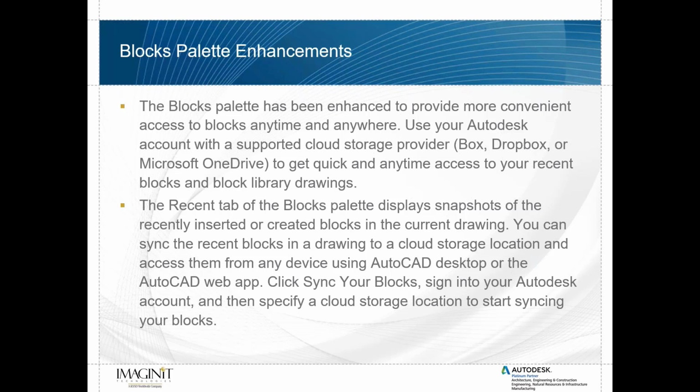The Recent tab of the Blocks palette displays snapshots of the recently inserted or created blocks in the current drawing. You can sync the recent blocks in a drawing to a cloud storage location and access them from any device using AutoCAD Desktop or the AutoCAD web app. Click Sync Your Blocks, sign into your Autodesk account, specify the cloud storage location, and start synchronizing your blocks.